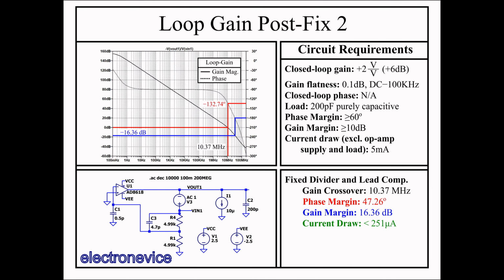With the tweaks we've made thus far, the gain crossover now occurs at a frequency 100 times greater than our maximum user frequency, so we should be able to accomplish this. This method is simply putting a resistor in between the op-amp output and the capacitor. This obviously has the immediate drawback of making the signal have a non-zero impedance value in our 100 kHz passband. However, this is often acceptable, especially if the load is capacitive like ours.